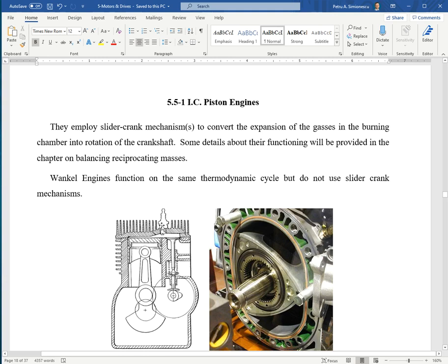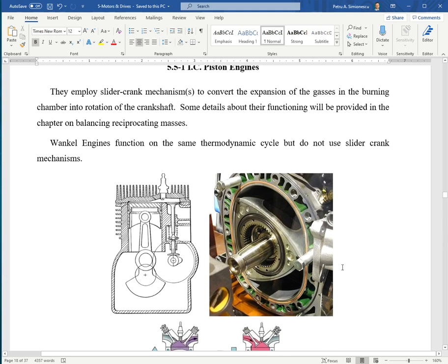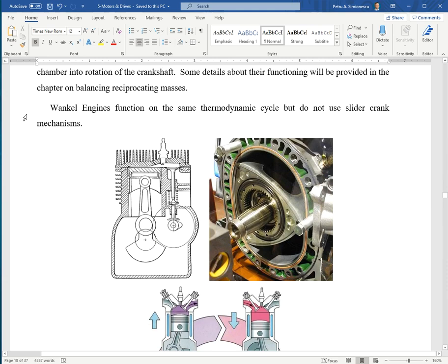There are engines other than those using pistons. There are the Wankel engines, and there are other designs, but this is the most common non-piston engine. It's used in some automotive applications. NSU, and Mazda, I think, used them. Here to the left is shown a side valve, also T-shape chamber, I believe it's called, piston engine, the type you've seen in many lawnmowers, a 4-stroke engine.